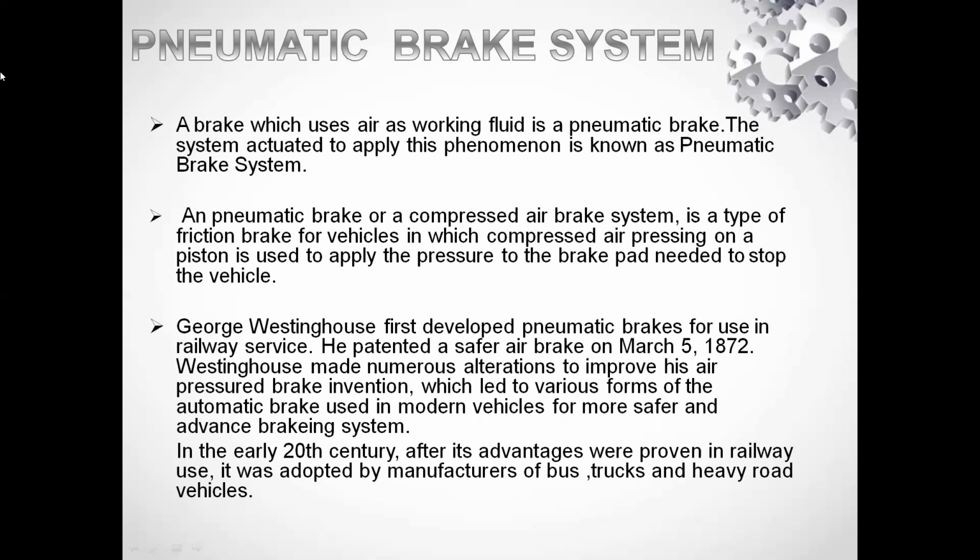A pneumatic brake or a compressed air brake system is a type of friction brake for vehicles in which compressed air pressing on a piston is used to apply the pressure to the brake pad needed to stop the vehicle. Already we have seen the mechanical braking system and the hydraulic braking system. In the hydraulic braking system we are using fluid. In the pneumatic braking system we are using air. So air acts as the working fluid in this pneumatic braking system.